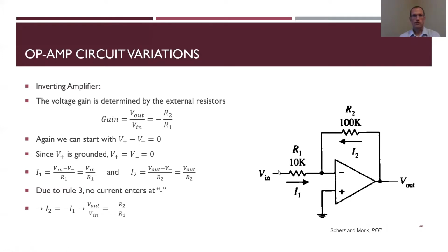An inverting amplifier. Inverting means I've connected my negative feedback loop into the negative terminal, and V in is in the negative terminal as well. So for this one, I have some current, we call it I1, coming across resistor R1 from V in into this joint, with the positive terminal grounded. And then on the V out, I have this negative feedback loop coming up. So I2 is going through some resistor R2 and hooked back up into the negative input terminal, V minus.